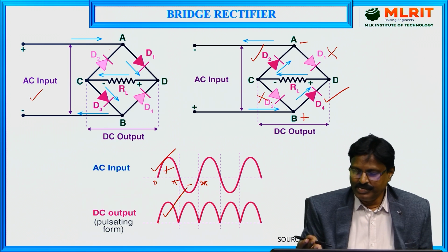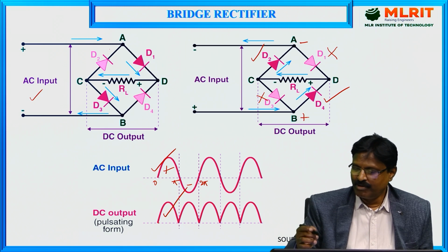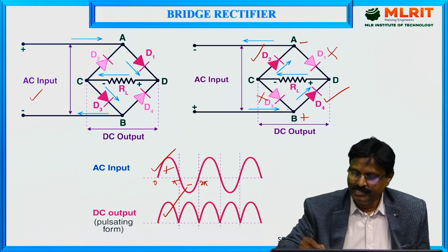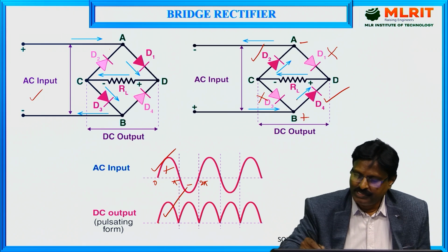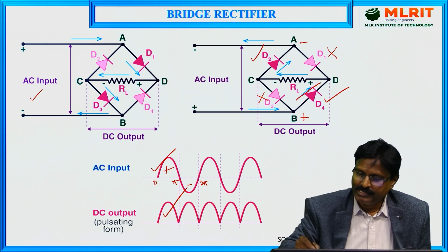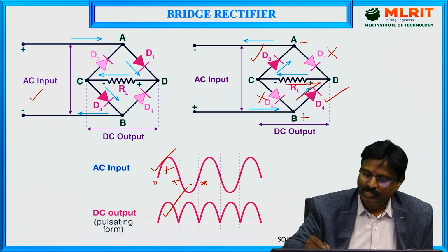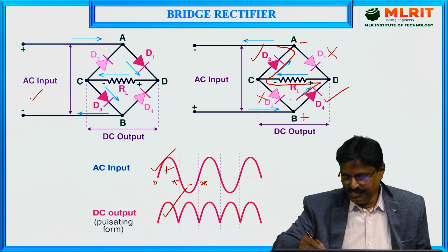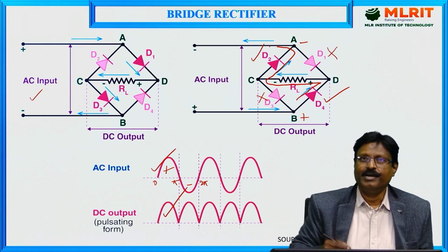Okay. So let us draw the current direction here, conventional current direction. So here positive means first the current will be started like this. The D4 is forward bias and a load resistor. It passes through the load resistance RL, and D2 is also forward bias and it will be reaching to the lower potential, that is a ground. Okay. So this is the direction of the current.